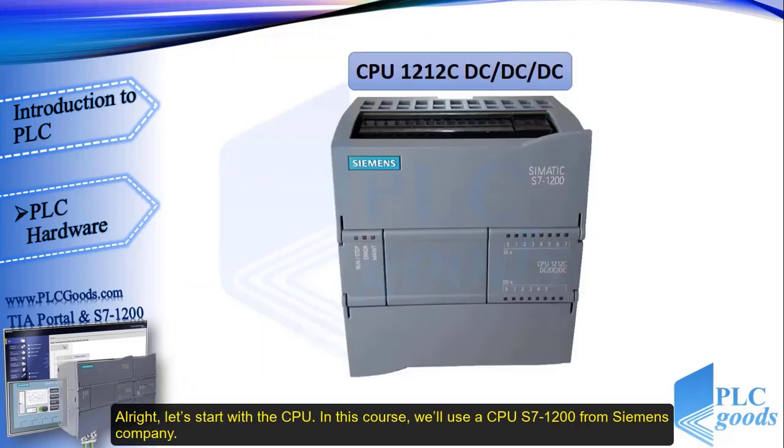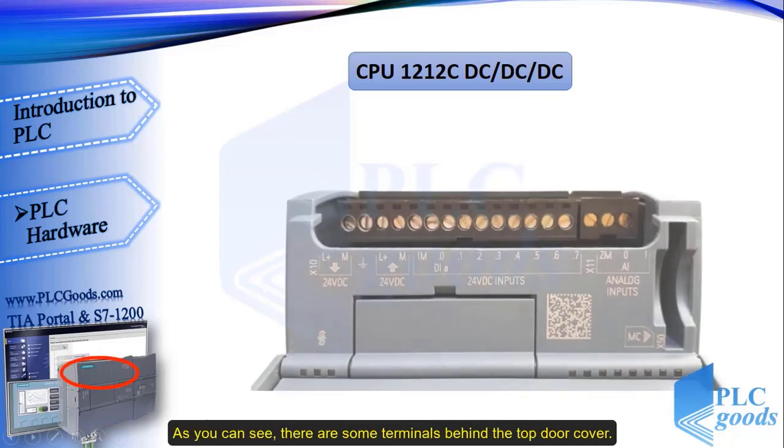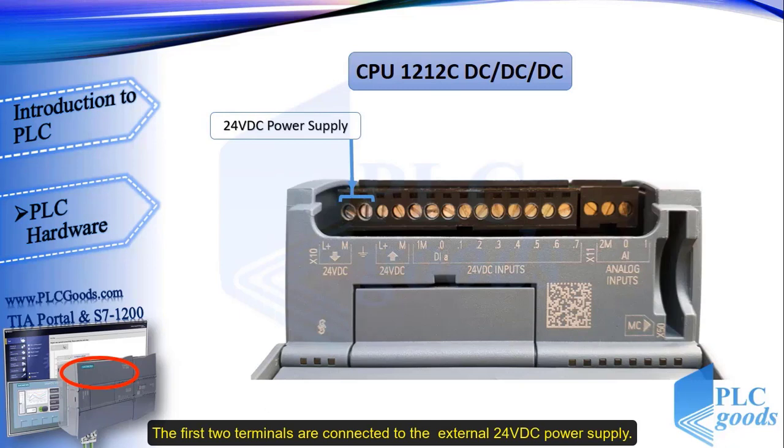Alright, let's start with the CPU. In this course, we will use a CPU S7-1200 from Siemens company. The Simatic S7-1200 controllers can be classified into 5 categories. In this tutorial, the S7-1212C model will be used. As you can see, there are some terminals behind the top door cover. The first 2 terminals are connected to the external 24 VDC power supply.